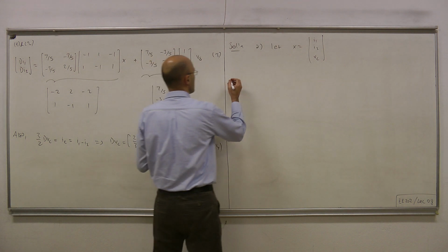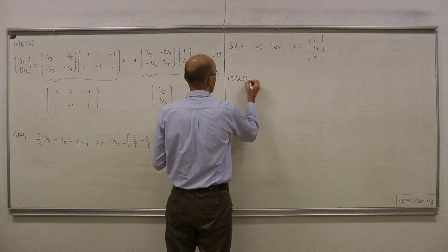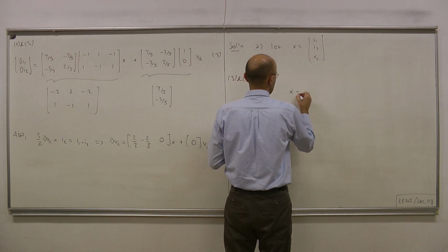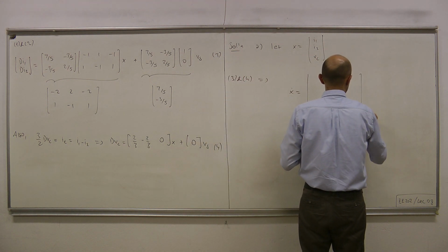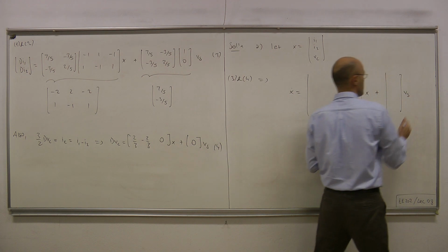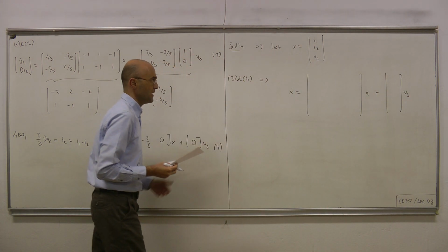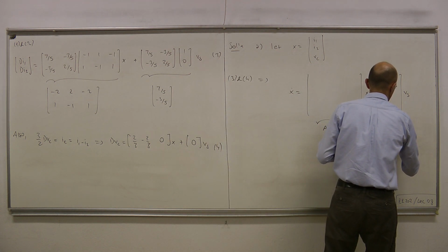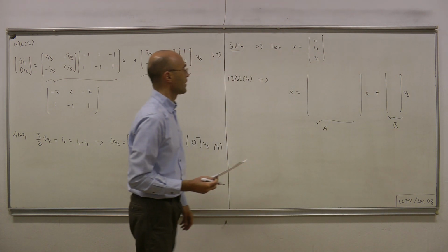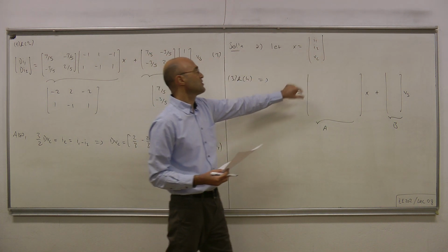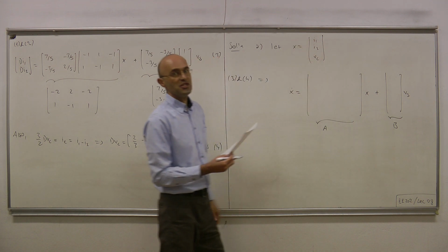So finally, 3 and 4 yield x dot equals Ax plus B Vs. This is our A matrix. This is our B matrix. Okay. Now x was I1, I2, Vc. Therefore x dot is I1 dot, I2 dot, and Vc dot.